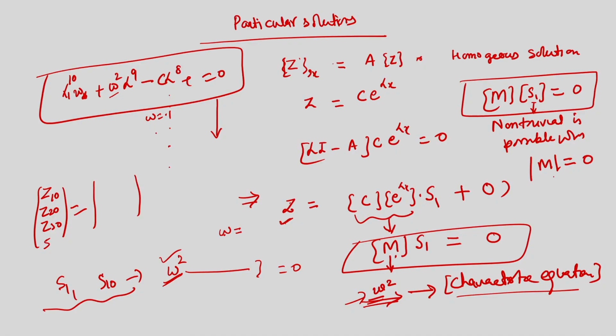This is the technique where the boundary conditions are to be satisfied in displacement form. So, basically if we say that my cylindrical shell is free, in that case Nxx needs to be specified, or N theta theta, Nxx and Mxx need to be specified. In the present case we do not have Nxx, Mxx as variables. So, we need to satisfy them in an average sense,